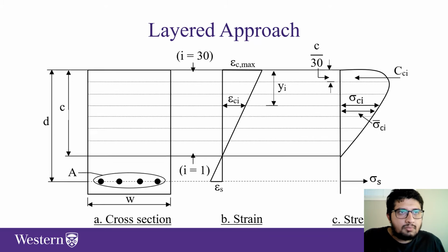And we can determine the distance from the extreme fiber to the compressive force in each region, and we can determine the moment due to the compressive force in each region. If we sum all the moments up, we get the total moment due to the concrete compression.